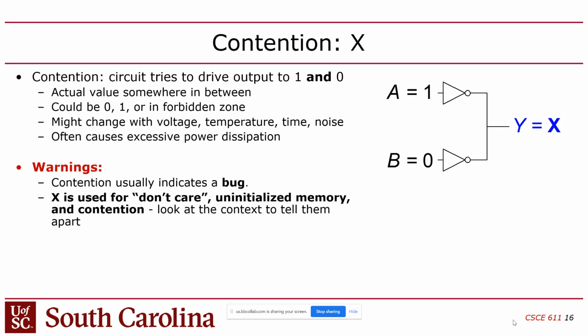which is where you have 2 drivers, 2 blocks of logic inside of one module, or it doesn't even have to be in one module technically, that could happen across the hierarchy. But if you have 2 pieces of logic that are trying to set different values to the same physical wire, or what would be realized as a wire in the deployed design, in other words, you have one piece of logic that's trying to put a 0 and the other one's trying to put a 1 on there, we call that double driving.